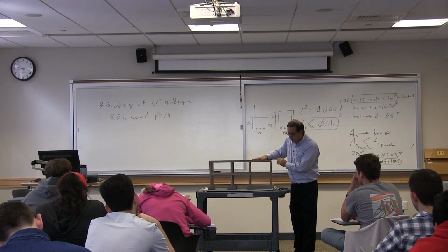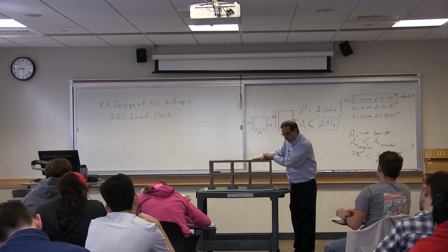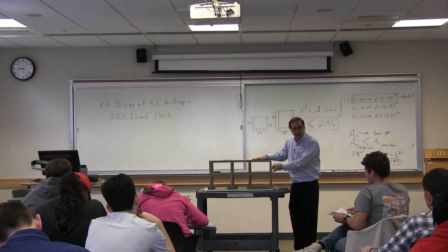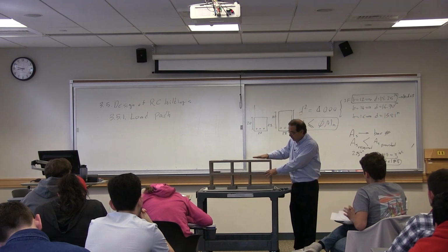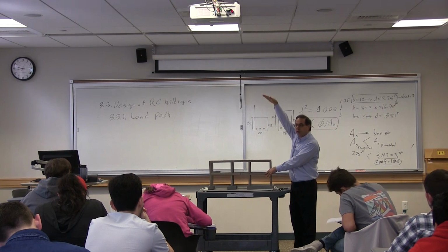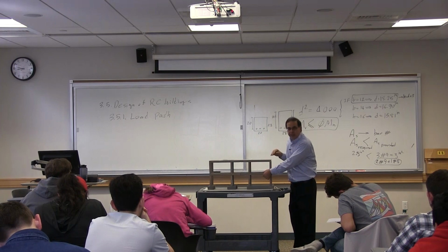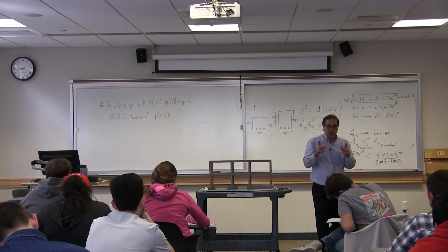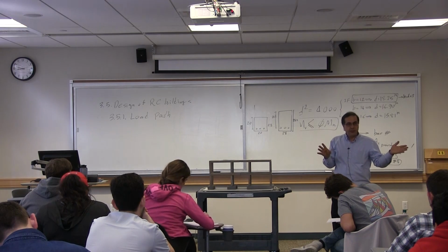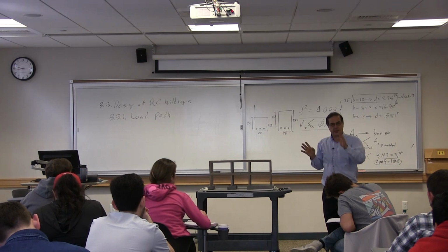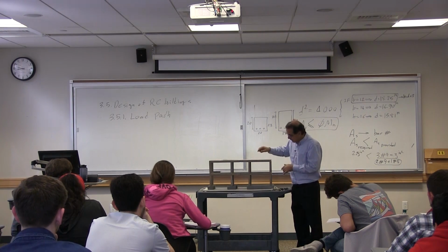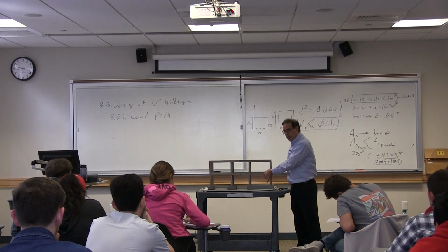So the load that I apply here, the effect of that gravity load on this beam is negligible. That is, if I have 1 story above or 100 stories above, it doesn't make any difference. Again, we are talking about only gravity load. Don't confuse that statement with lateral loads. Lateral loads are different. For gravity loads, let's say this beam is 20 by 20.